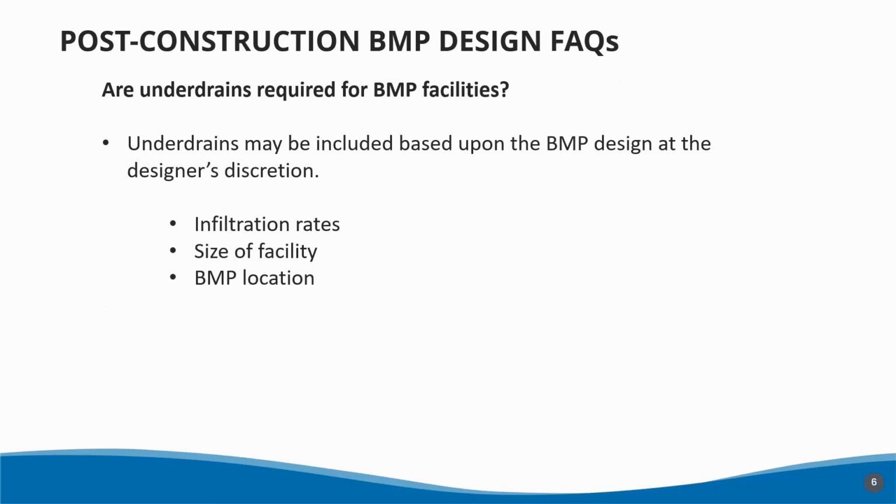Typically, if your facility is small enough or if infiltration rates are high enough, then there's no real risk of it ponding, and the discharge would be high enough. The underdrains do help to distribute the flow throughout the facility. So if it's a larger facility, you definitely want a system in place so that it can reach through different areas, the far corners of your BMP.